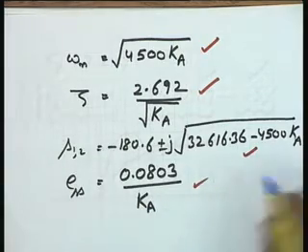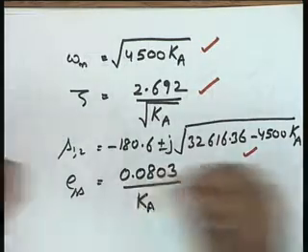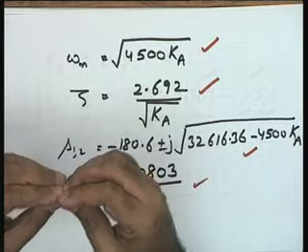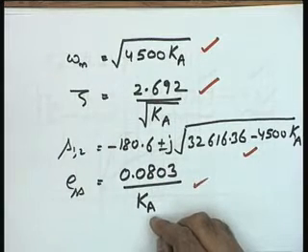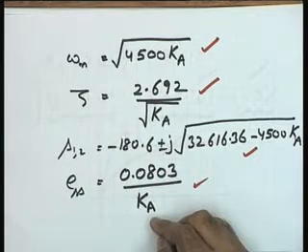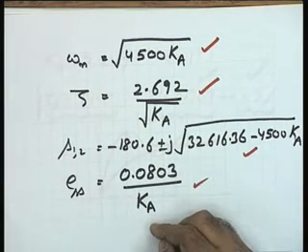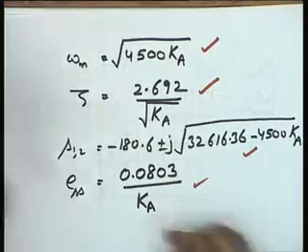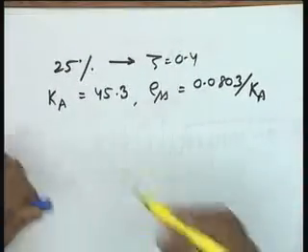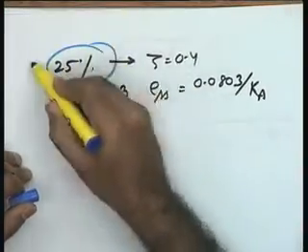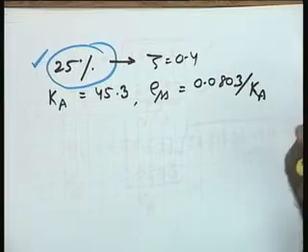So it means the situation of a trade-off will come, where you will say that no more values of Ka if the peak overshoot is exceeding the limit you have imposed on the system. After all, otherwise the system may become unstable. Let me say that the limit you have imposed on the system is that your peak overshoot should not be higher than 25%.